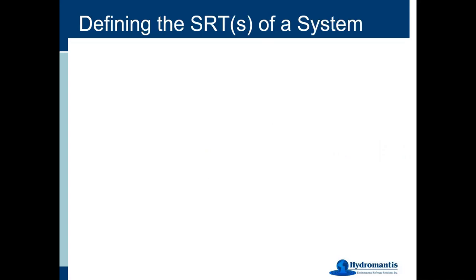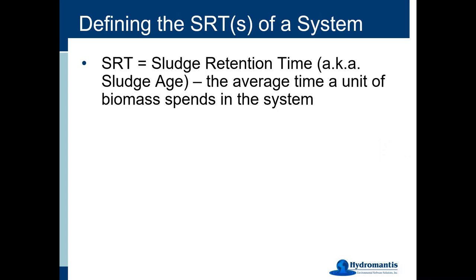Okay, so now moving on from mixed liquor to SRT. So SRT, just to remind everyone, in this case I'm talking about sludge retention time, or solids retention time as some people refer to it. It's the sludge age. It's the average time that a unit of the biomass spends in that system. How long does it sit there and grow before it gets wasted away or goes out in the effluent? As you know, of course, this is a really key, very useful parameter in looking at wastewater treatment plant design and operation. It tells us how long that biomass is going to be there growing, and we know that certain aspects require a certain length of time in order to be able to do their job.